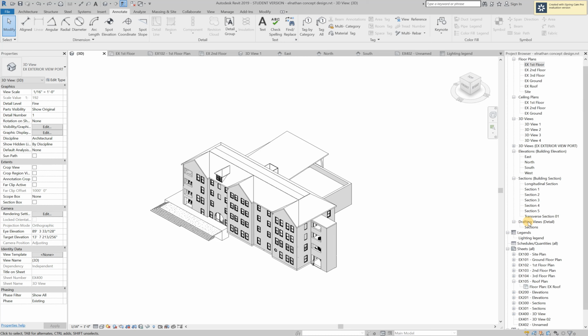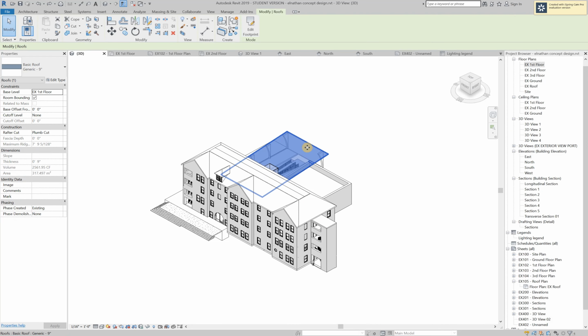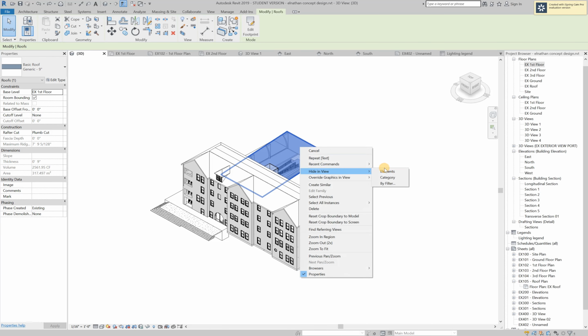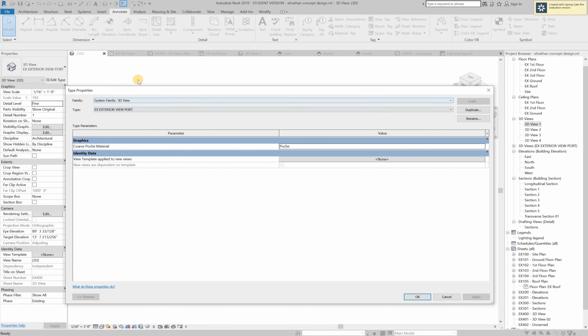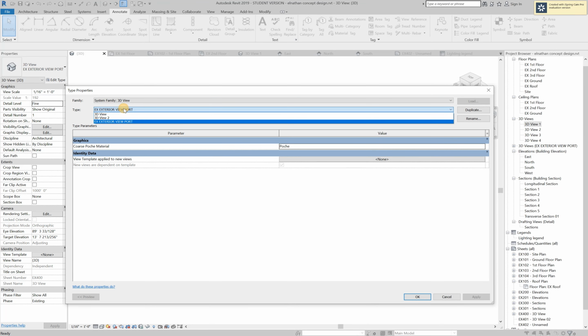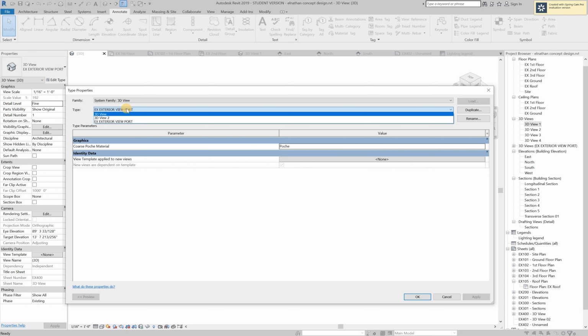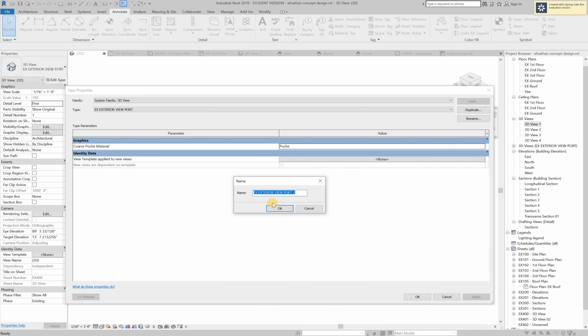Again, this is a view under the 3D views. This is the main model. So if I edit something, like I want to hide that in view, but I don't want to lose this information, I could go under 3D views. I could go under the properties, edit type, create a different subsetting under the 3D views, and you can duplicate that if you don't like what you have.